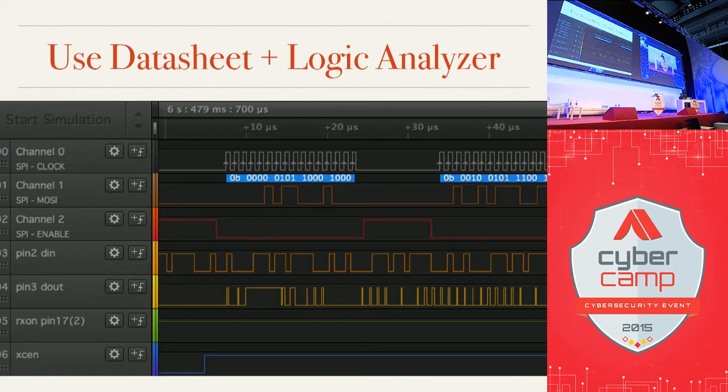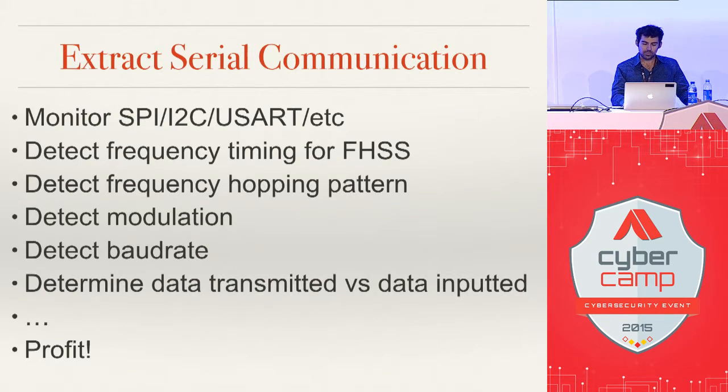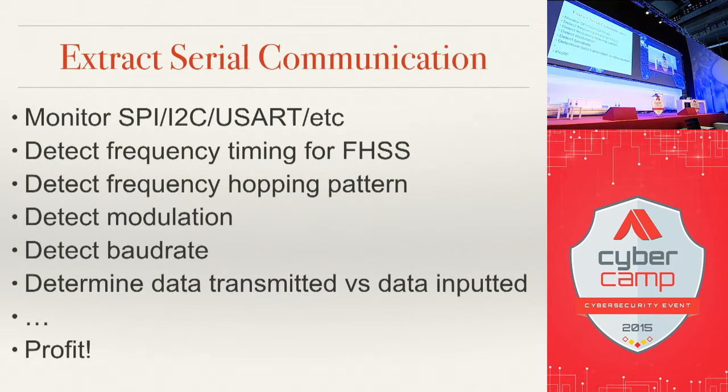So I can use the logic analyzer to start analyzing every other pin. I can say, okay, this pin is clock, this one might be data, this one is serial data in, data out, and I can start extracting all of that communication. From here, I'll monitor all of the serial communication: SPI, I2C, UART, USART. For something that's frequency hopping, I can actually see the timing. I can see how often it frequency hops, what that pattern is, and what frequency it's hopping to.